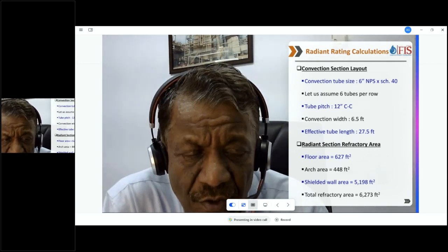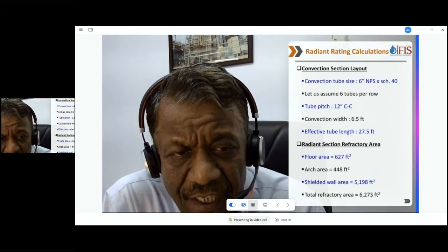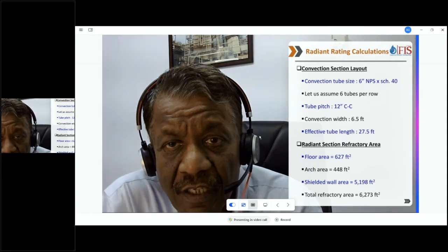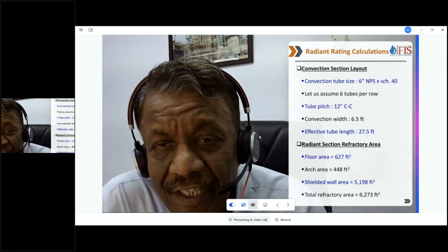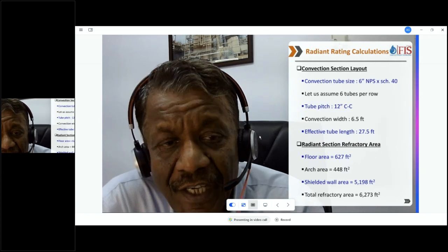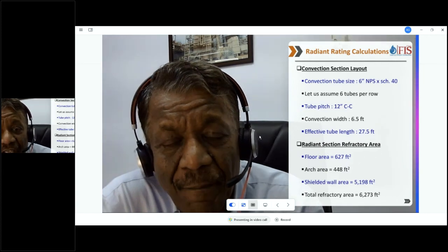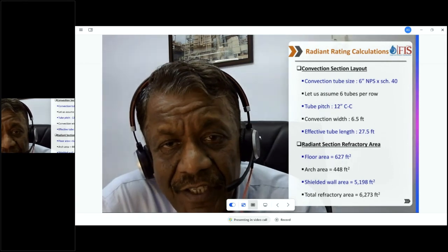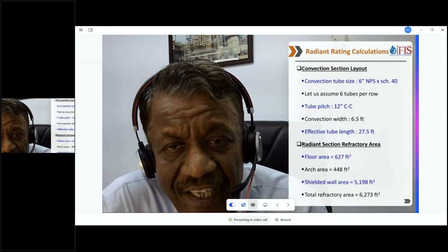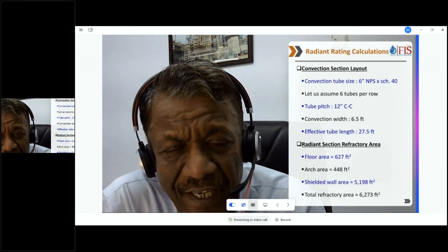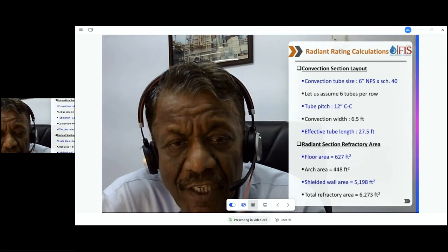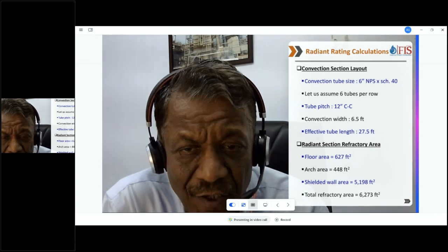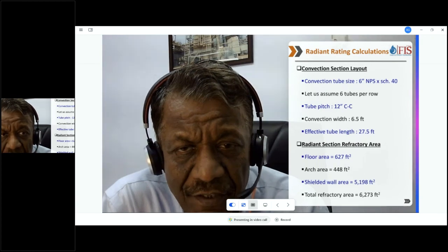So it's a very, very simple technology, and it can be done in almost every heater. So is inclined firing compliant with API 560? Yes. There is nothing in API 560 which says you cannot do it, and we have done this in about 15 heaters. I think 6 are in India and 9 in the US. And it is our default, in all our new heaters we are putting inclined firing, and it is the way to go.